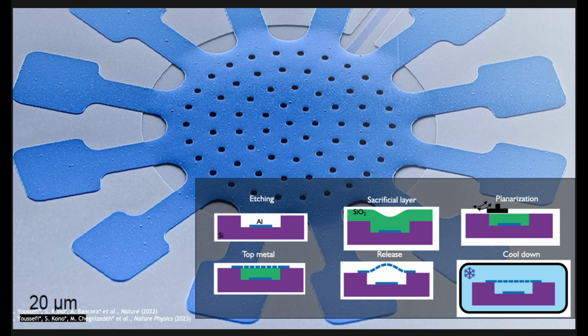otherwise we would not see these quality factors. One of the things we wanted to try, so we recently came across niobium. We found out that at low temperature there can be as much as 1 gigapascal stress. And for aluminum, the yield stress is about 200 megapascal. So we think with niobium top plates, we could probably increase these quality factors substantially by increasing the stress.